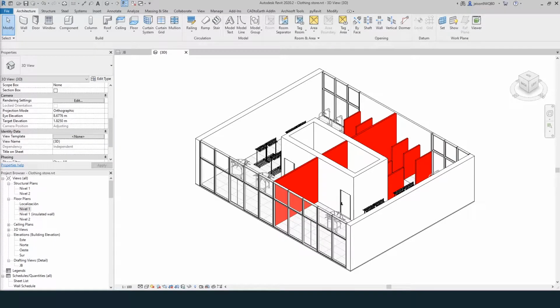Filters are another view configuration and customization tool that can be developed and applied in Revit project templates. They're similar to the filters available in schedules in that they can either display or hide elements matching user-specified criteria. However, filters can also override the graphic appearance of elements within a view. The possible combination and application of view filters is virtually limitless.